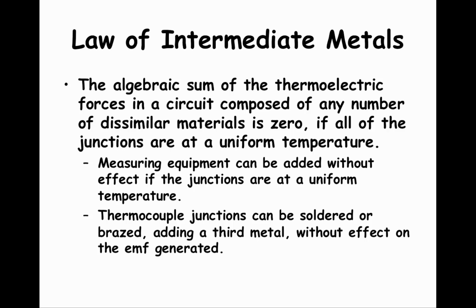A second consequence is that we can use solder to make thermocouple junctions, and the third metal does not affect the EMF generated. This is great news because this makes it easy to make junctions in the field using normal soldering techniques.